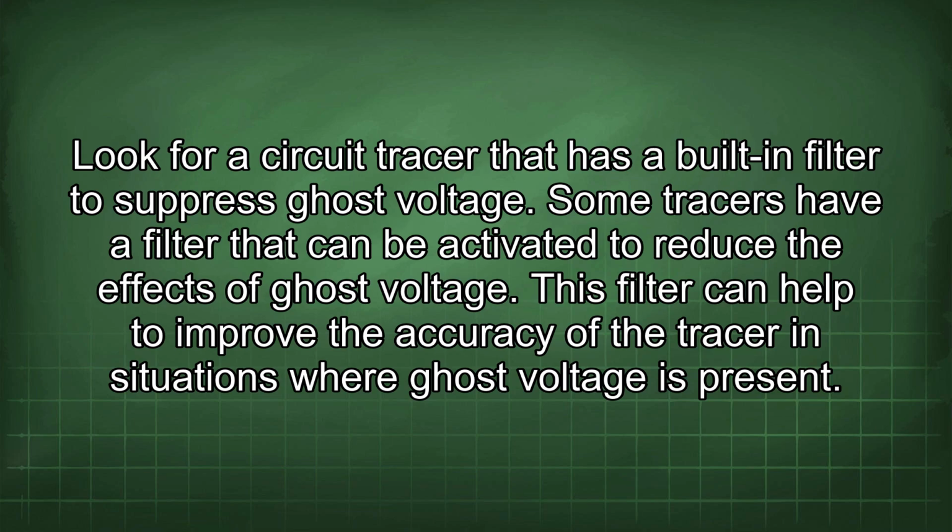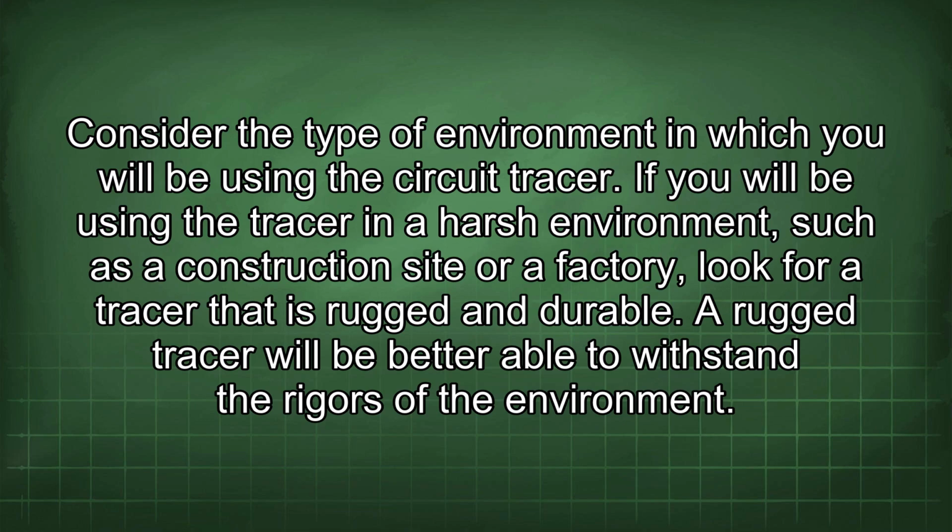Some tracers have a filter that can be activated to reduce the effects of ghost voltage. This filter can help to improve the accuracy of the tracer in situations where ghost voltage is present. Consider the type of environment in which you will be using the circuit tracer. If you will be using the tracer in a harsh environment, such as a construction site or a factory, look for a tracer that is rugged and durable. A rugged tracer will be better able to withstand the rigors of the environment.